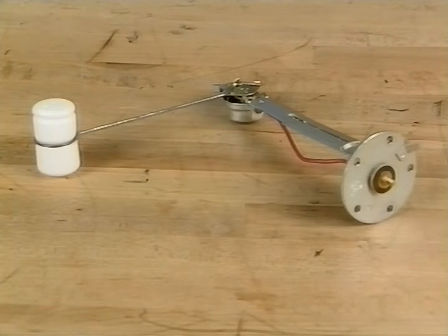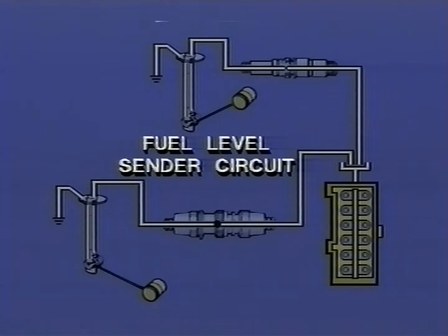The final input devices for the electronic instrument panel are the fuel level senders. These senders operate in the same manner as those on other tractors, by varying resistance through the movement of a float. When a tractor is equipped with both senders, the EIP averages out the readings so the portion of total fuel remaining is displayed on the bar graph.